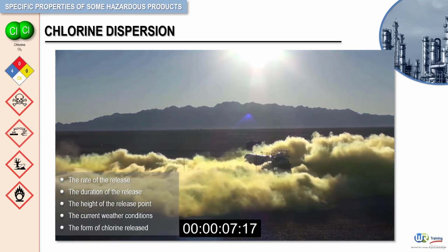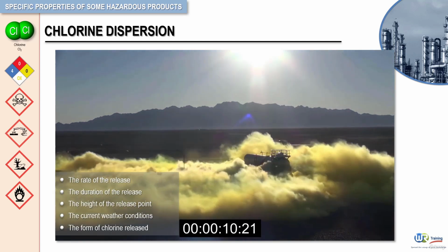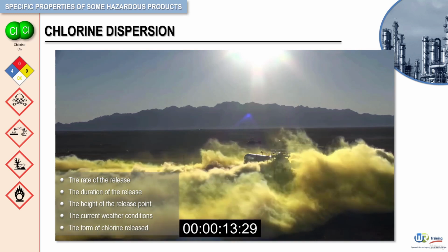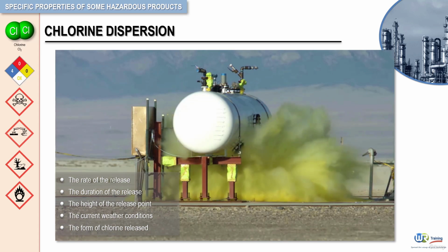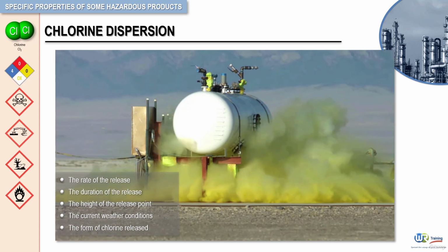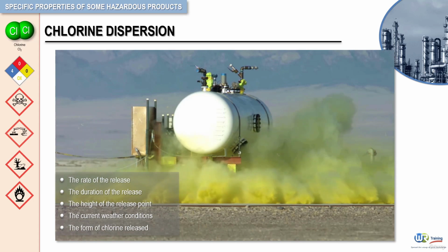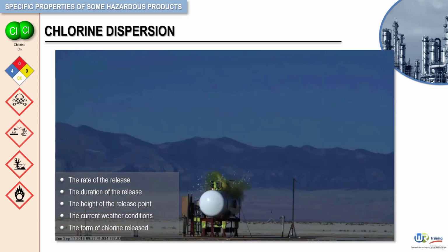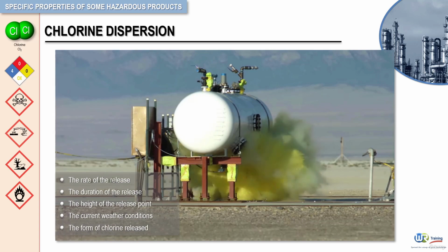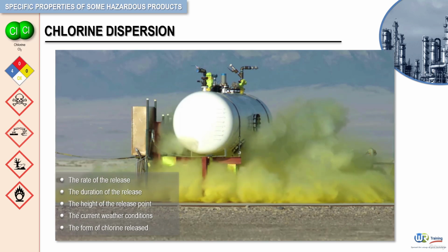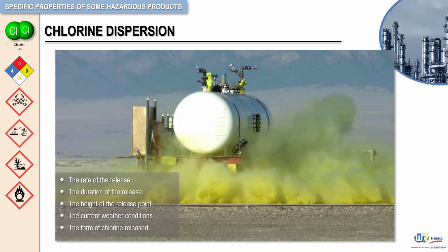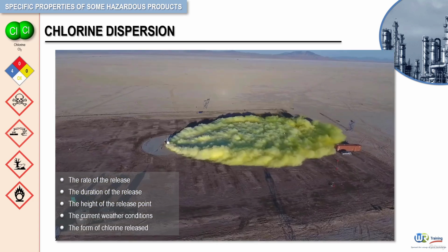While the responder most likely will encounter chlorine as a gas, emergency plans should take into account the possibility of the release of liquid chlorine. The location of the leak on the container will determine whether liquid or gas or both will be released to the atmosphere. If liquid chlorine is released from a small puncture or hole, it will most likely instantaneously become a gas. When pressurized liquid or gas is released from a container, the temperature and pressure inside will decrease, and in turn will reduce the release rate. This phenomenon of decreased temperature is due to the changing pressure condition of a breached chlorine vessel.